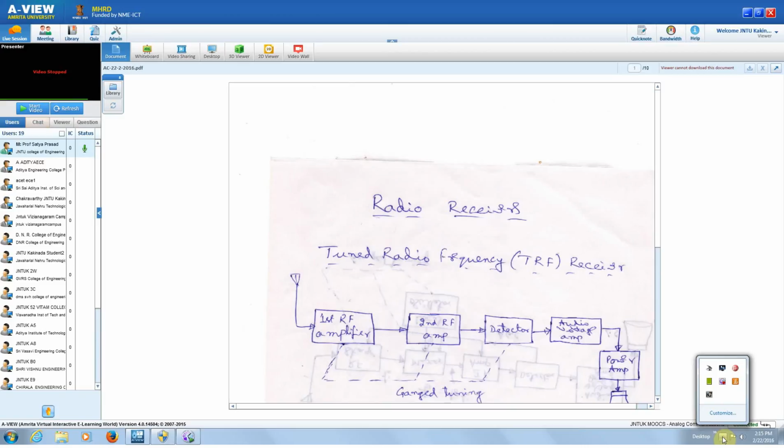to this 800 kilohertz. We said that each AM station has a bandwidth of, what is the bandwidth of an AM station? 10 kilohertz, because we said that it is plus or minus 5 kilohertz. Now we have the baseband audio signal frequency limited to 3.3 kilohertz, with required guard band and so on, so that the adjacent channel signal or transmitter signal will not be interfering with this. We said that each AM station will be having 10 kilohertz as the bandwidth.